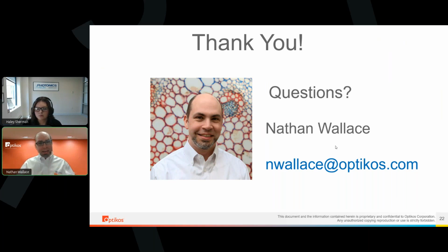The only caveat here is that when I go to make one of those adjustments, I have my three spheres of contact. I adjust one of those, and I am going to tip my lens. So there's a little bit to think about there. Alternatively, you could think of maybe you have a floating setup that you're then going to bridge and bond or put on some other mechanics around that's going to constrain that lens in place.